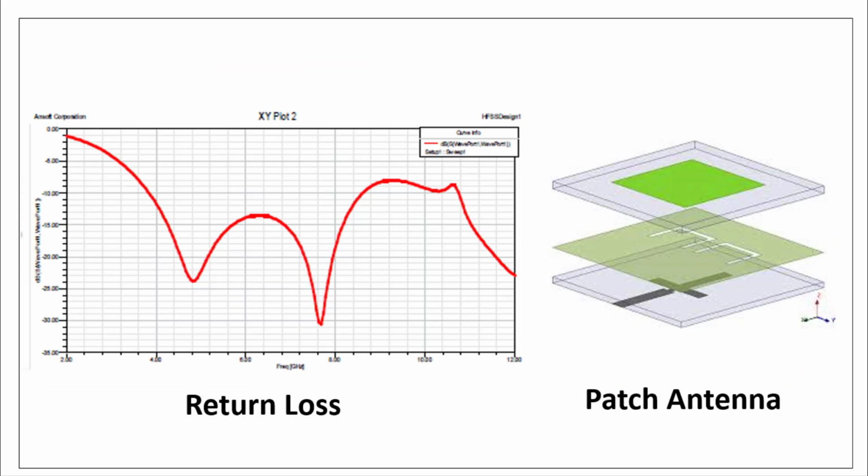We have another example of a multi-layer antenna. Here we have the substrate at the bottom in black color, and the feed line used to feed the radiating element in green color. We have a ground plane between these two substrates, and a radiating element in green color. In the ground plane we use two slots in the form of the letter U. So this is a technique used to find ultra wideband characteristic, the multi-layer antenna.